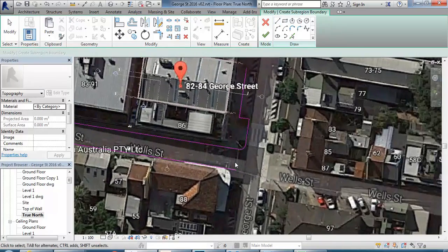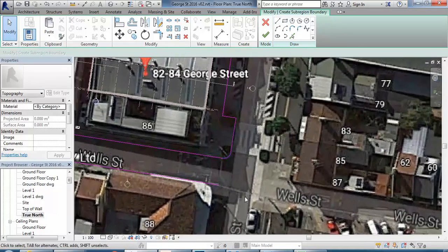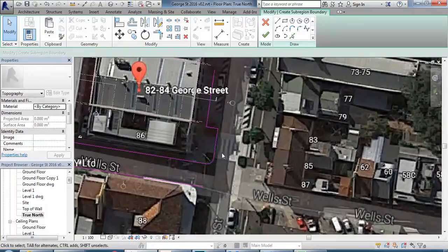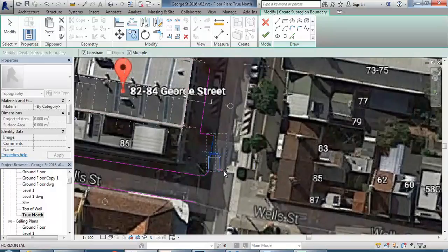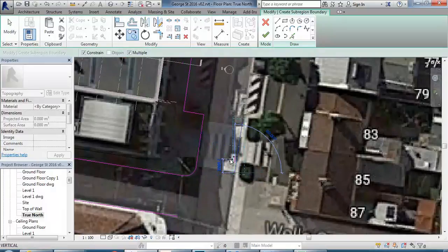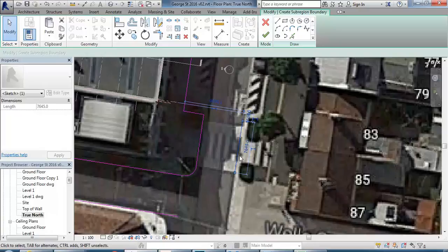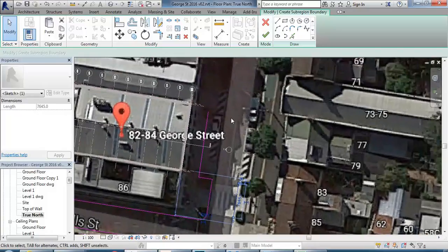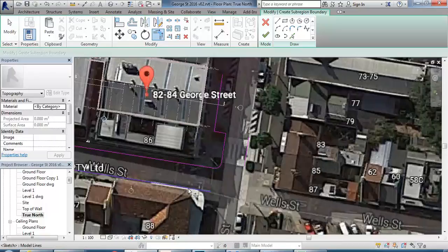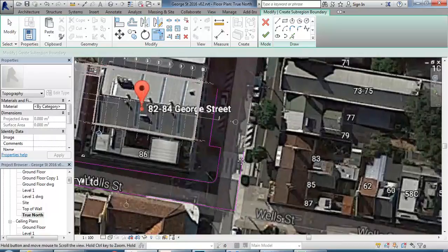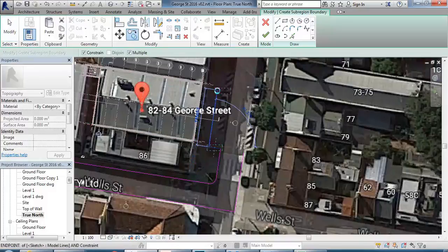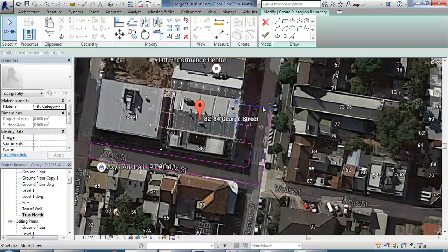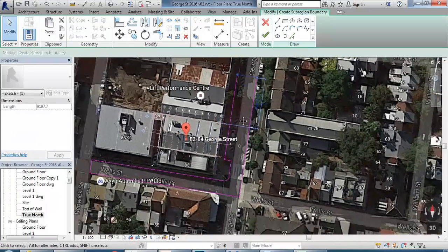Okay, so very quickly there, got some sort of basic road, and I won't do the whole intersection. I'll just do the other side here. Join them together. And actually just copy this one and I'll get a closed shape. So it has to be closed like most things in Revit. I won't let you finish it until it is. Just extend that a bit.